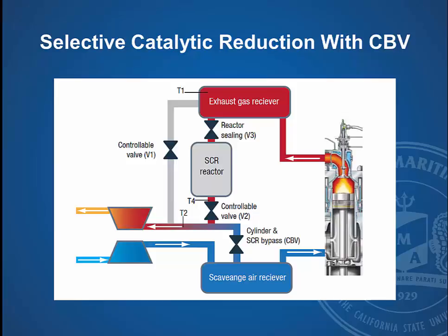And with that, since you decrease the mass flow rate, you're going to increase the exhaust gas temperatures out of this engine. And then that SCR bypass will be adjusted back and forth to maintain the exhaust gas appropriate for entering the SCR reactor. That is under development, but the reason for this is to try to use it at lower operating speeds.